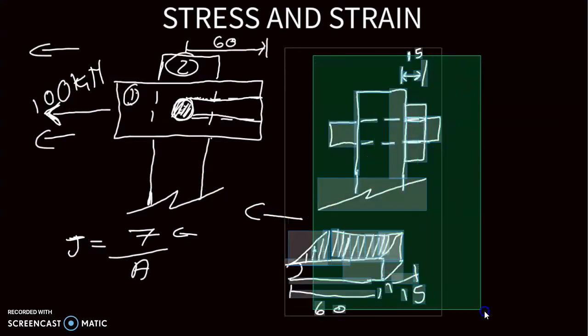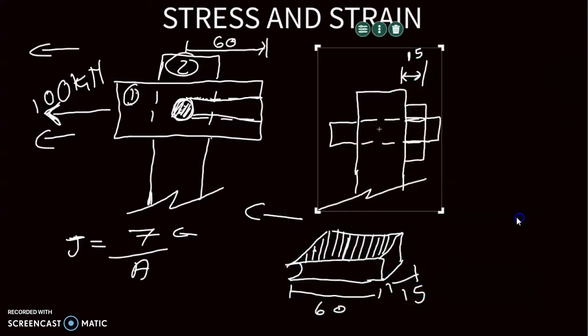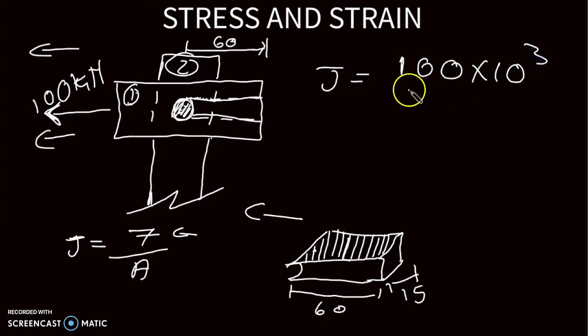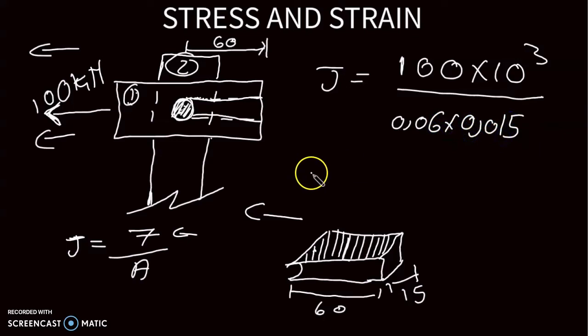I'm going to erase this. We'll need that. Let me just erase this. So we know stress is calculated by what? Force divided by area. What's the force? 100 times 10 to the power 3 divided by, what is the area? 0.06 times 0.015. This is the area that we are dealing with.